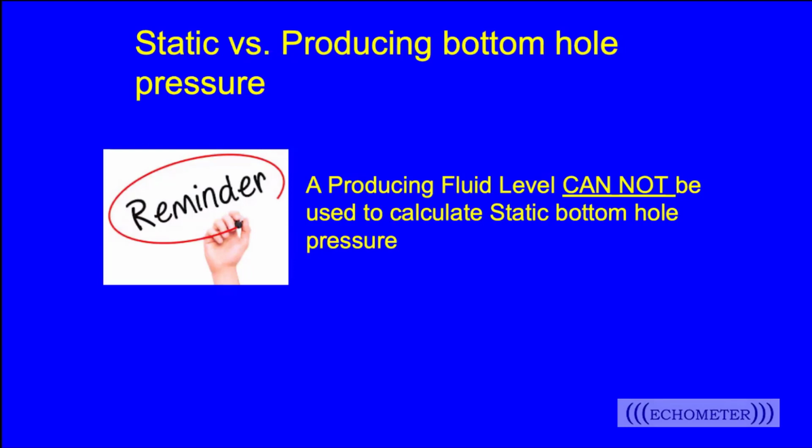A number of us have worked with customers on producing shots where they obtain a producing bottom hole pressure, and then they turn around and say, well, the program can calculate a static bottom hole pressure. Let's calculate a static from the same shot. That's not true. We have to shut the well in long enough to static that out. And that depends on the area that you're working in, how permeable the reservoirs are. That depends how long that's going to take. And we're going to get into that in a few slides.